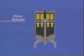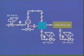There are some designs in which the pressure on both sides of the piston is varied to control valve position. These actuators are said to be double-acting, and they require the use of a four-way positioner. Of course, there are reverse-acting designs as well. For now, though, let's look at the pneumatic arrangement for a direct-acting piston-actuated control valve that uses an air spring.